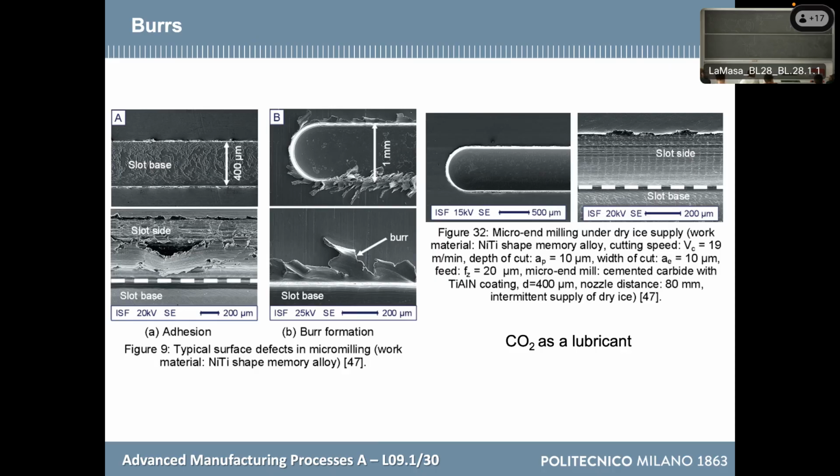Micro cutting can do a nice job even on glass, even on ceramics, because of what we have seen about the big pressure that we are applying when plowing. This is something that you should have studied in metallurgy. When you have a fragile material and you put it under pressure, and it is better if you have the same pressure you could have at the bottom of the sea, so pressure in all directions, even a fragile material tends to behave like a ductile one. It is like the pressure helps it to be tougher, or not to break.